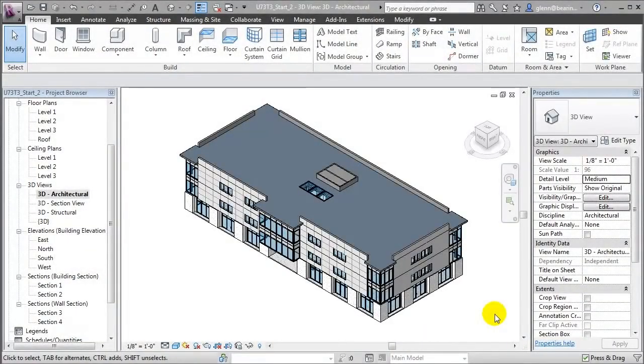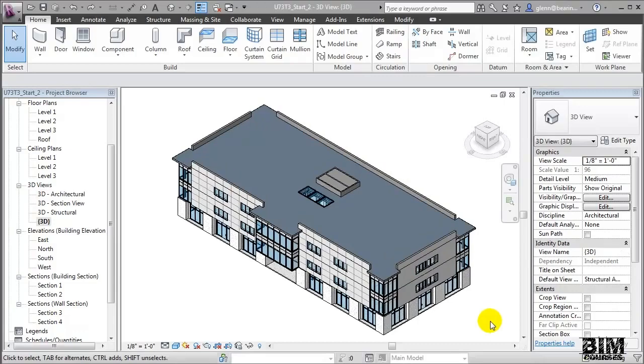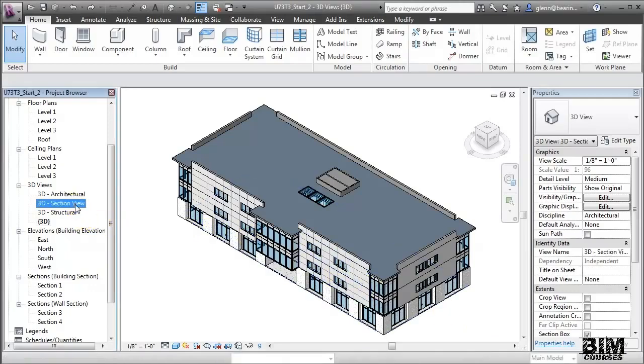Autodesk Quantity Takeoff provides powerful tools for creating a detailed quantity takeoff by extracting quantities directly from your building model. The process starts with opening your building model and exporting it as a DWF file that will transfer into Autodesk Quantity Takeoff. For our example, we'll be working with a small 3-story building with retail space on the first floor